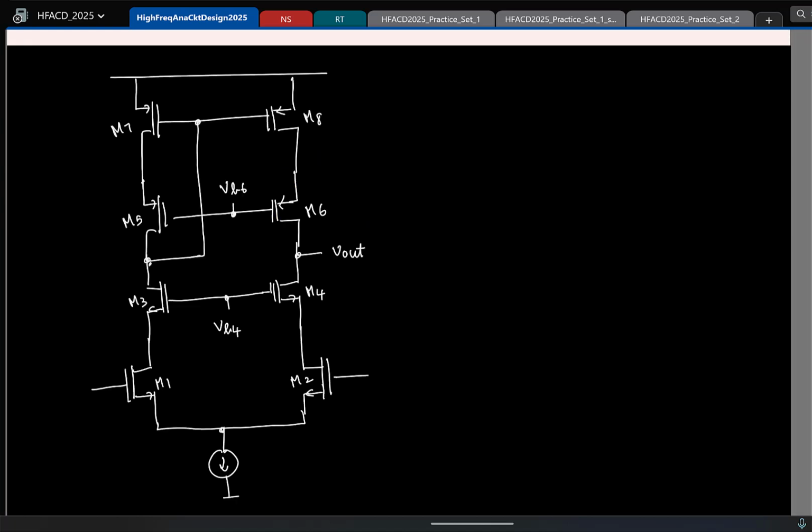So the idea is I want to make sure that the current flowing in the PMOS is equal to the current flowing in the NMOS. Now we can argue the same way. If the PMOS current is greater, this voltage will keep increasing. Correct. Now as a corrective action, you are supposed to reduce the PMOS current. That will mean you have to go and increase the gate voltage here. So this is something you want. This is something that's already happening. So you just go and connect.